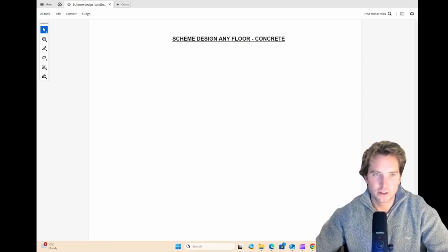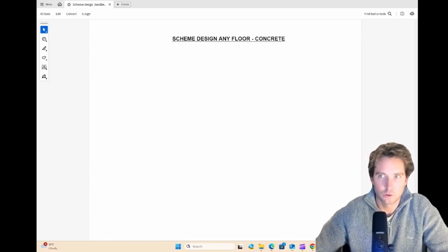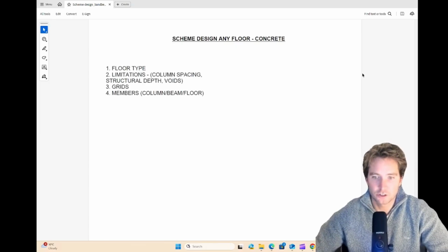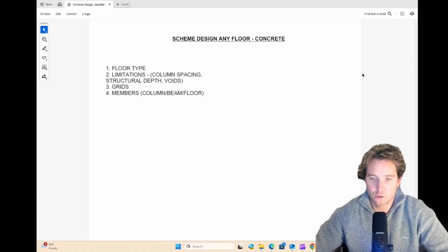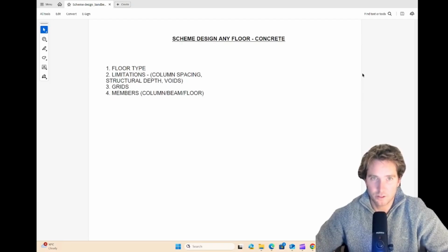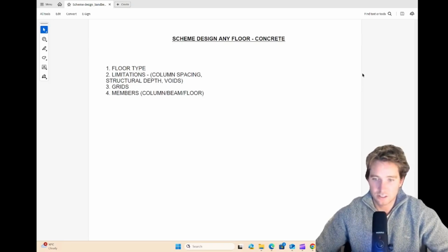What's up YouTube? In this video, I'm going to share the 4 steps that I use to scheme design any floor. So the 4 steps, firstly, the first thing you're going to do is just choose a floor type. Secondly, you're just going to have a look and make sure that you understand the limitations that you have to satisfy, whether that be minimum column spacings, maximum structural depths, or any voids, transfers, etc. that you sort of need to navigate.